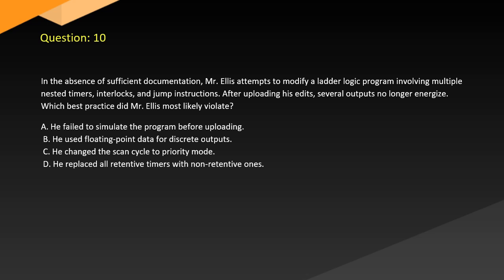Question 10. In the absence of sufficient documentation, Mr. Ellis attempts to modify a ladder logic program involving multiple nested timers, interlocks, and jump instructions. After uploading his edits, several outputs no longer energize. Which best practice did Mr. Ellis most likely violate? A. He failed to simulate the program before uploading. B. He used floating point data for discrete outputs. C. He changed the scan cycle to priority mode. D. He replaced all retentive timers with non-retentive ones.